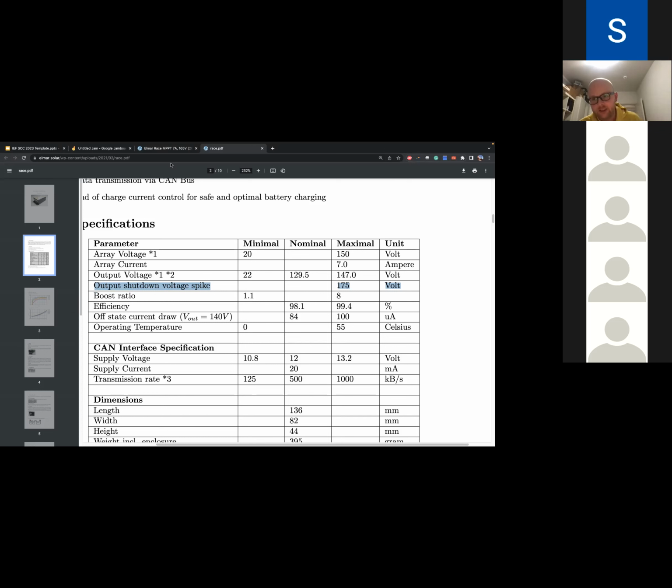Usually your output voltage is pretty fixed because the battery voltage doesn't change rapidly. Therefore, by changing the duty cycle, you can change the ratio between input and output voltage, and because the output voltage is fixed, you can choose the input voltage by selecting a duty cycle. Does that make sense so far?